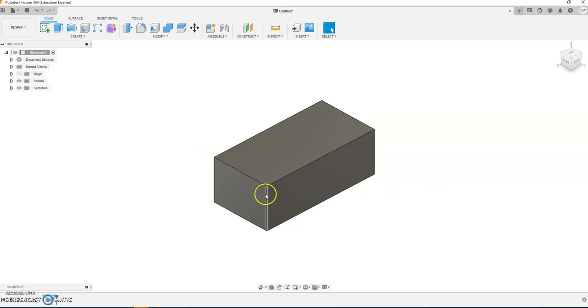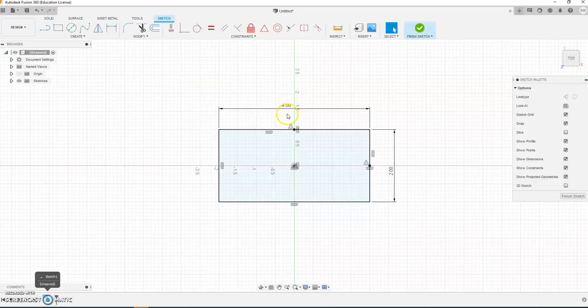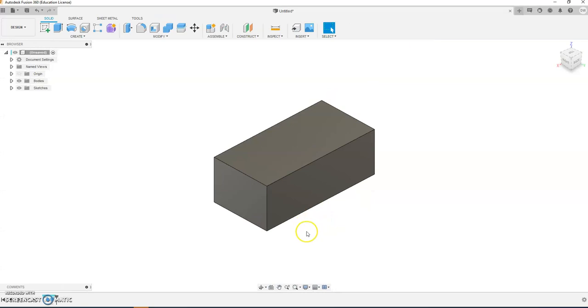If it's the wrong shape and it's really too wide or just the wrong shape, maybe you made a mistake on the dimensions. So come over here, hover over this piece that says sketch. Let me pause there for a second. It's not saying sketch, but trust me, this one says sketch if you hover over it. There it is, sketch. Double click on that and maybe change your sketch. Maybe you didn't have it 4x2. Change it so where it's in is the correct measurements there. Once that's done, finish your sketch, and it updates it to this drawing.